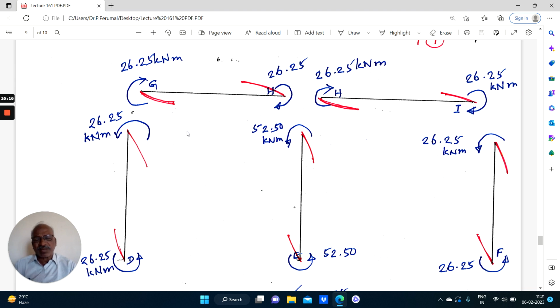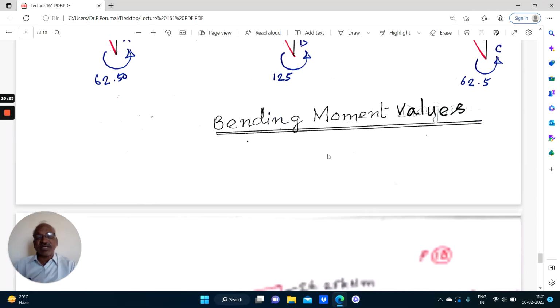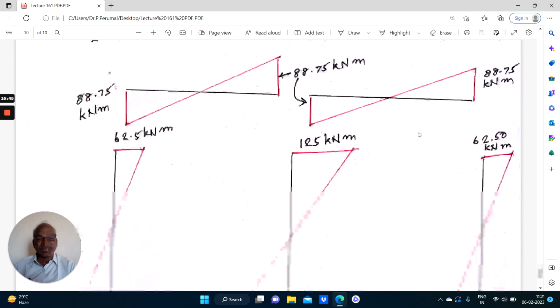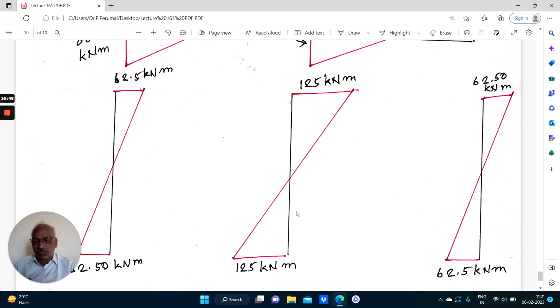You have done a number of problems, same procedure, right? So with this calculation, you will be able to straight away draw the bending moment diagram. On the tension side, you will have to plot the bending moment. No load, no other moment, therefore straight away it is a straight line. This is the bending moment diagram, because for individual members we have drawn the bending moment diagram. You can combine everything and you can draw a single bending moment diagram. So that completes actually this shortcut.